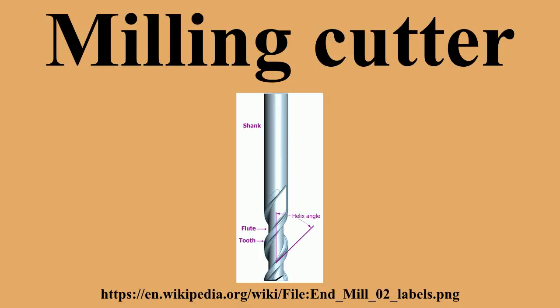Hollow mill. Hollow milling cutters, more often called simply hollow mills, are essentially inside-out end mills. They are shaped like a piece of pipe with the cutting edges on the inside surface. They are used on turret lathes and screw machines as an alternative to turning with a box tool, or on milling machines or drill presses to finish a cylindrical boss. Dovetail cutter. A dovetail cutter is an end mill whose form leaves behind a dovetail slot, such as often forms the ways of a machine tool.